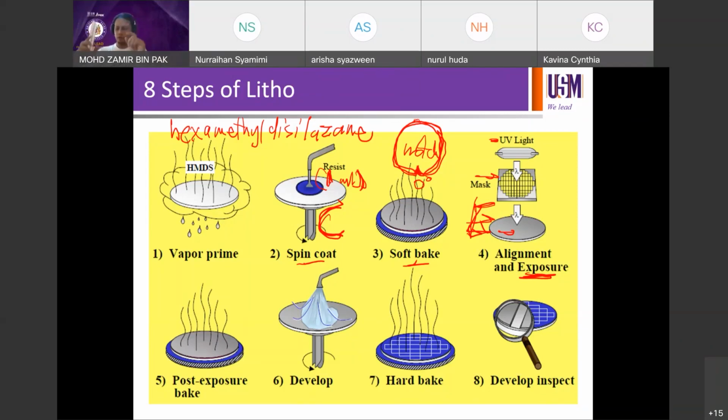Later I'm going to share with you the stage processing before we expose. It will do some alignment, which we usually call global alignment. It will find the home position. Once it fixes the home position, say the notch is at the bottom, only then can it print the vertical pattern like this matrix. Just imagine if you don't have notch alignment, it cannot align, and your wafer will come in at any theta.